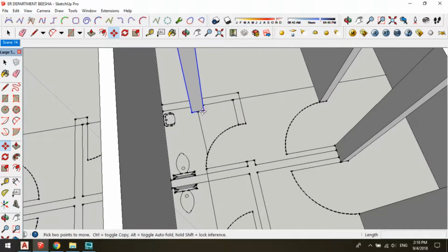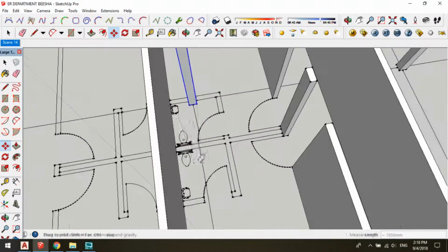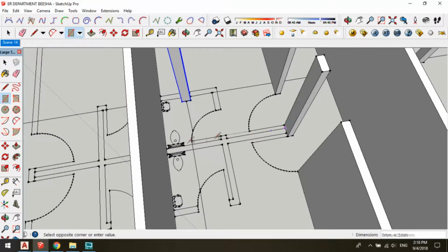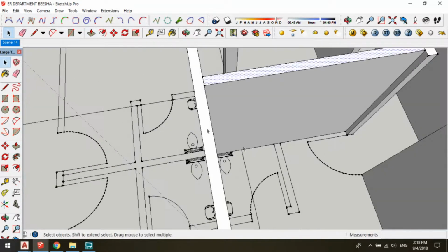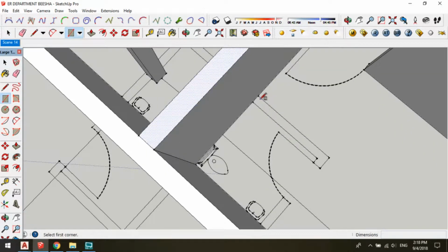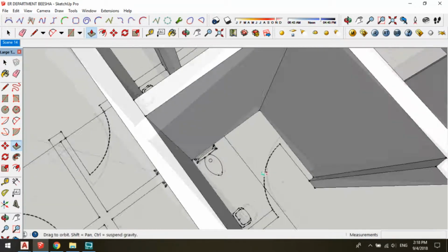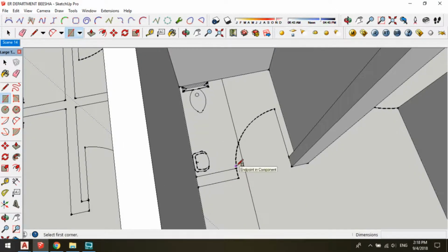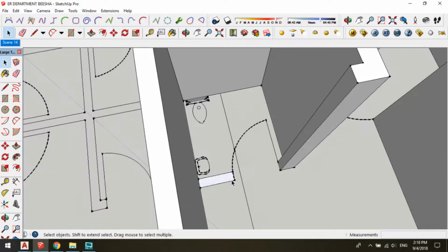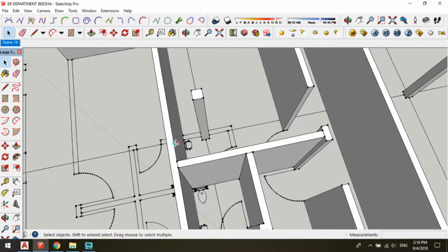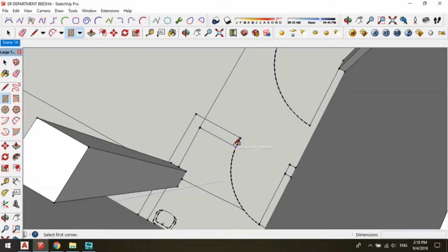Okay, so let's click the post, put it there. Is it really a post? There is no post here. Okay, create a rectangle and push it, point it to the top of the wall so it will have the same height. Create a rectangle, delete the unnecessary lines, push it, click R for the rectangle command, and click on the first point and the other point.